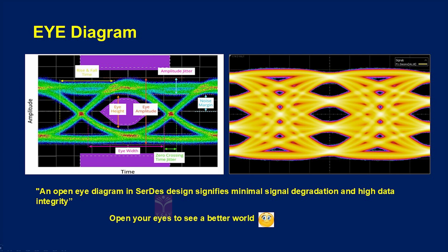An open eye diagram in SerDes signifies minimal signal degradation and high data integrity. The right side image is an eye image for an advanced SerDes. This is a non-return to zero (NRZ) SerDes, maybe PCIe Gen 3 or 4 based, or maybe a USB SerDes eye diagram. But on the right side we talk about PAM4 based. We'll come to that in a short while.